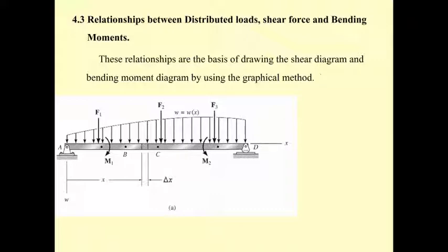We also like to see the change of the bending moment along the length of the beam and the frame, and we draw the bending moment diagram. After finishing drawing, we can determine the maximum shear force and the maximum bending moment, and later we may design the beam and the frame based on the maximum moment and the maximum shear force.